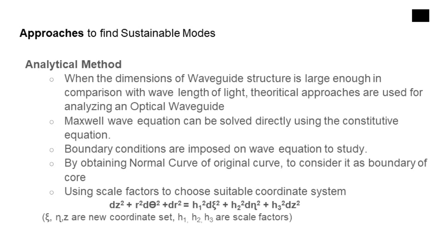Apart from this, even in solving the scalar wave equation, there may be difficulties because of other factors. In some non-circular cross sections, sometimes it is difficult or even impossible to separate the variables in the scalar wave equation. This is generally due to the nature of the geometry of the guiding structure and the refractive index grading of different regions of the waveguide considered. The other problem is to solve the differential wave equation which is obtained after the separation of variables, because of the presence of singularities.